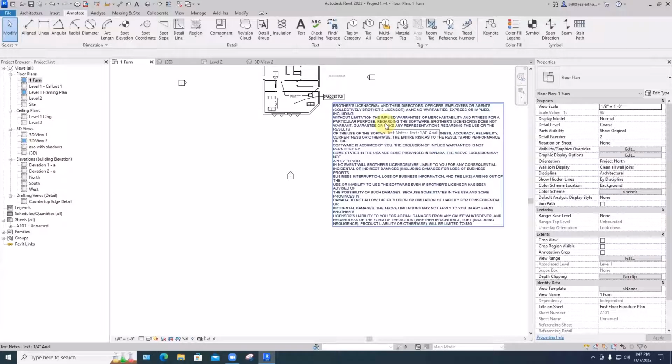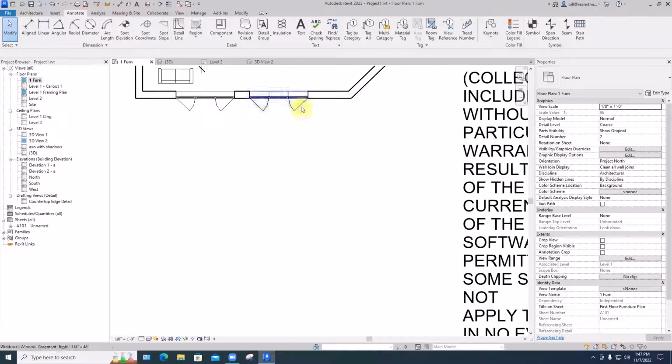Well, we really won't get into that till next semester, about putting a real construction set together. But typically, if this were something important about window weatherproofing, you would have a list, let's say your second sheet would be specifications for this project. You have windows, and you have all windows shall be such and such. And then over here in the drawing next to the window, I just have a keynote for number 1 and go there, and then it's by reference. So you only have to update it one place.